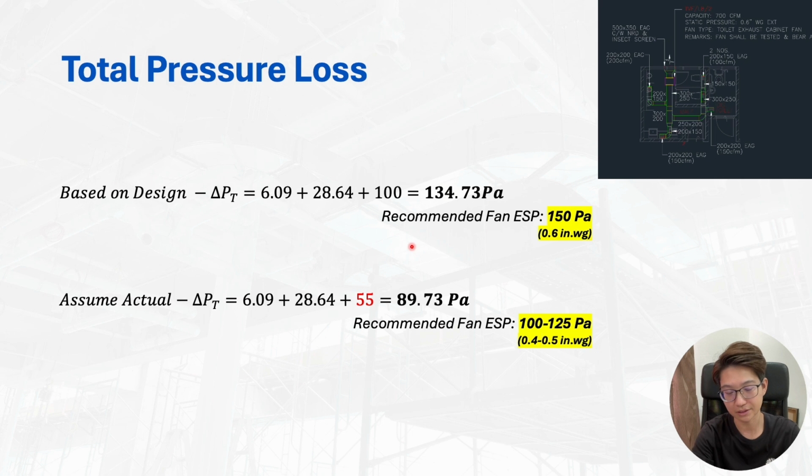And usually we want to counter check after you design, since you use a lot of estimation. Let's say the contractor submits the shop drawing, the actual installation drawing. Then you see from there whether or not the duct deviates, the duct size, the transition, whether they change from sometimes butterfly fitting to 45-degree entrance. So you know whether or not you want to recalculate the static pressure or respec the fan. And you see whether they submit enough static pressure for the ductwork and all the equipment. After all the selection, we want to reassess the whole calculation.